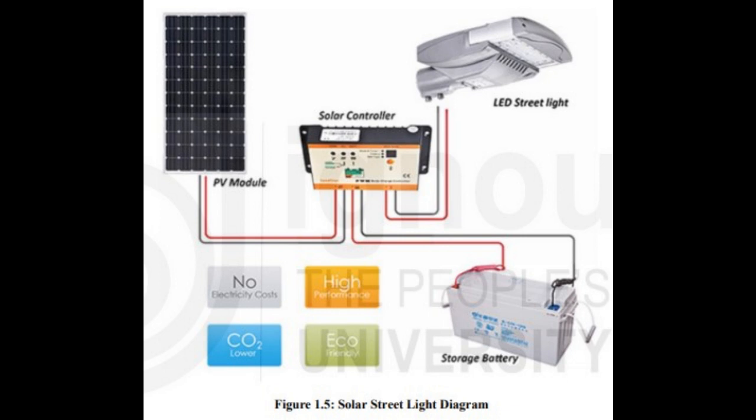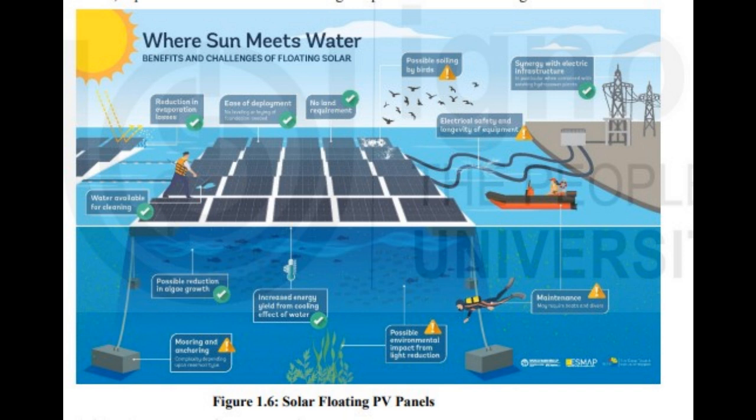Cons: The initial investment is higher compared to conventional street lights. Snow or dust, combined with humidity, can accumulate on horizontal photovoltaic panels and reduce or even stop energy production. Rechargeable batteries will need to be replaced several times during the life of the fixtures, increasing the total cost of the life of the light.